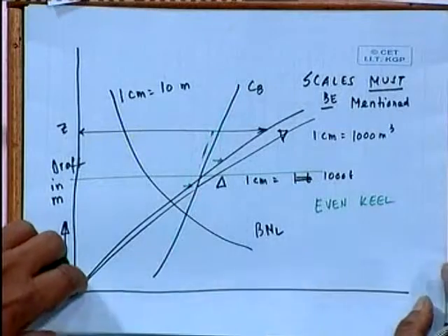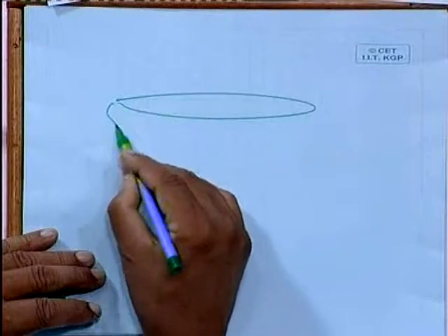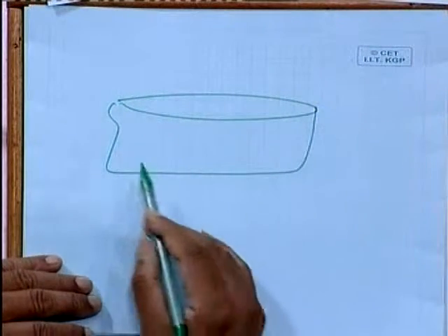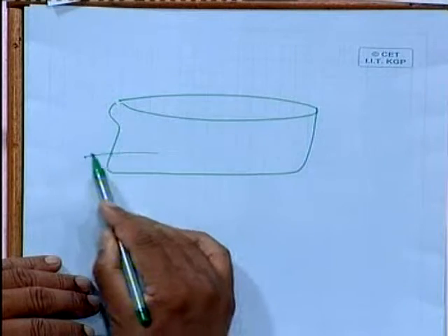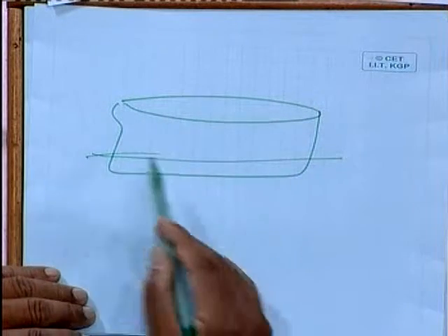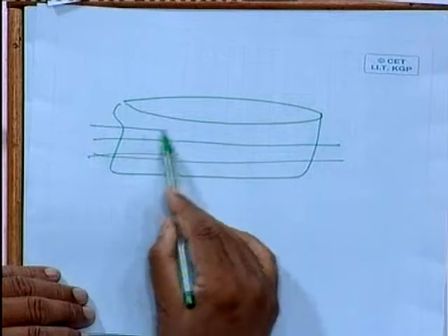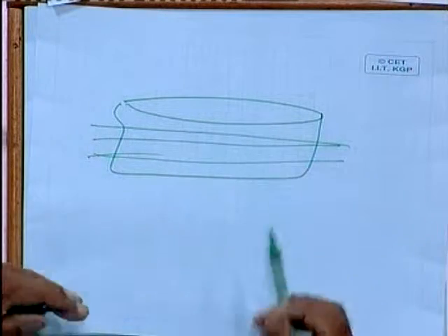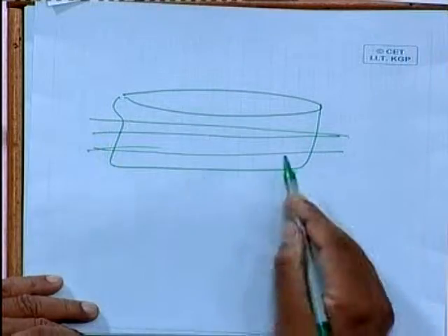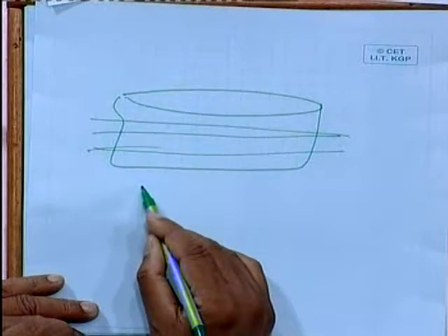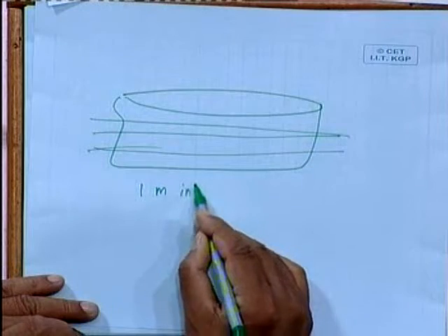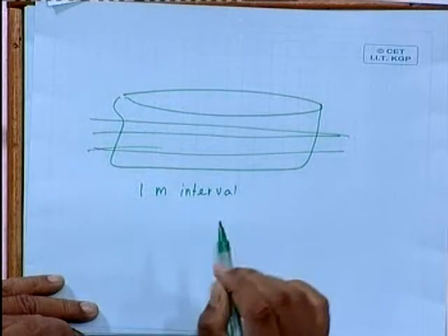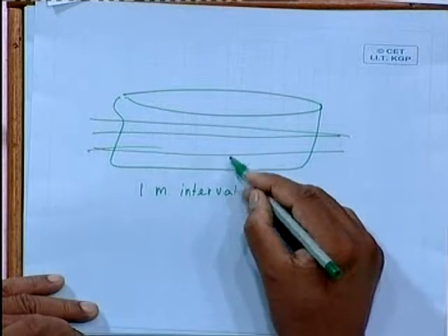because what we have done is that we have got a ship here. We assume that okay, what will be the property if it is under 1 meter water line, what if it is under 2 meter water line, what under 3 meter water line. We have not done the calculation for trim. We really cannot do it because there is numerous variation. You cannot do for every possible line. So normally you are doing for say drafts at 1 meter interval